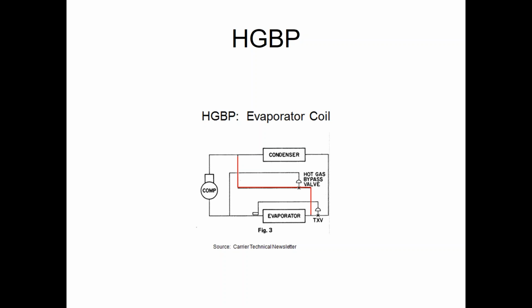It's just kind of a capacity control thing so we can keep the system online. We're not frosting or freezing evaporator coils, all that kind of stuff. So it's an older, completely inefficient way of capacity control or maintaining an operating envelope of pressures that's suitable to keep the evaporator clear of frost and the compressor happy.